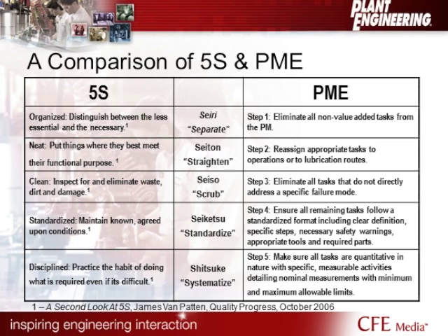Now the next one you see is scrub. And in the scrub section, we're going to eliminate all the tasks that do not specifically address a failure mode. So we'll talk a little bit about RCM a little later, but one of the key components of that is going through and doing a failure mode defects analysis. In other words, looking at how an asset might fail. And if I understand how it will fail, I can get to those specific failure modes, and then I can see if my PMs actually line up to address those failure modes. If they don't, they're probably non-value-added tasks, and we need to revisit those.